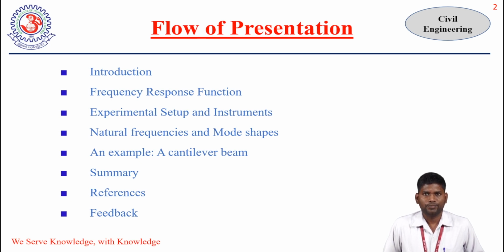So, here, Introduction. What is experimental modal analysis? Experimental modal analysis is a technique used in structural dynamics and mechanical and civil engineering to determine the dynamic characteristics. It tells the condition of any structures, any civil engineering or mechanical structures or aeronautical structures. This contains natural frequency, damping ratio, and mode shapes of a structure through experimental measurement.